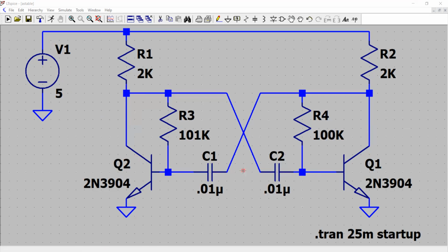It is an oscillator circuit, and therefore we don't require an external input signal to the circuit, such as the one we use for an amplifier. This is an oscillator, a time waveform generation circuit, and it doesn't require any external input except the DC power supply.